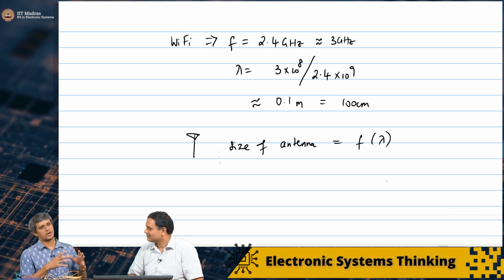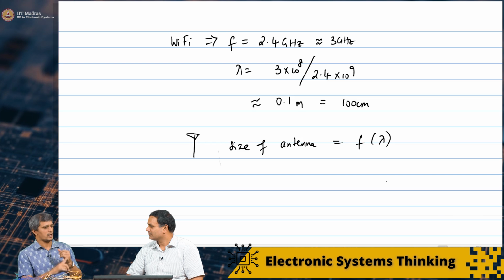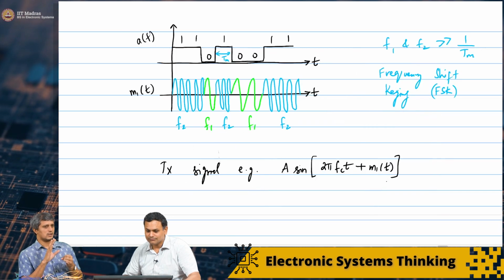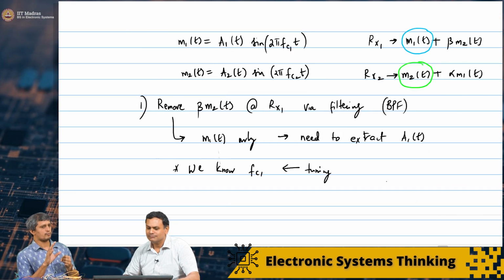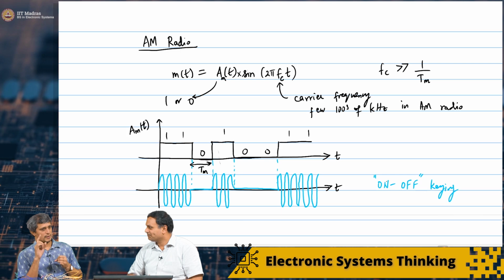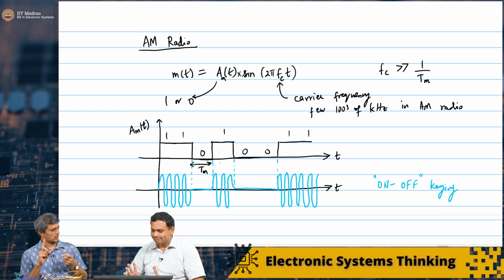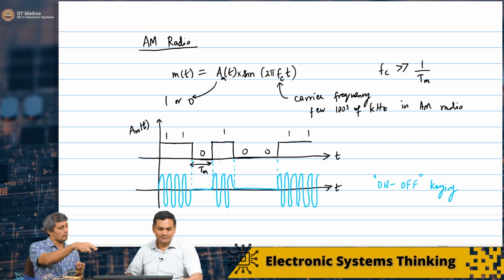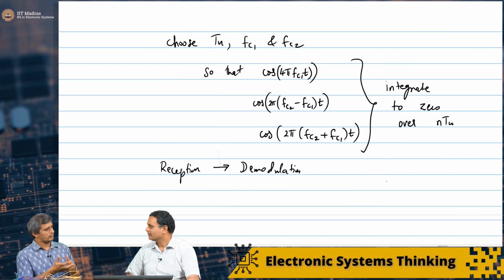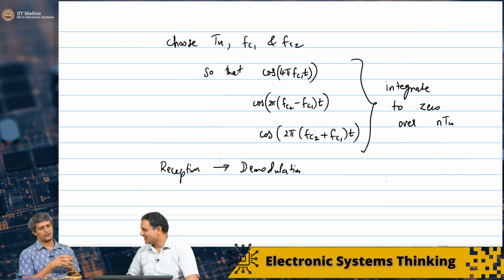I think we have covered the theory in reasonable detail. The primary takeaway is that it is just elementary trigonometry that governs amplitude modulation. There is nothing fundamentally limiting in terms of power. The modulation is not for the sake of power. It is basically to keep your signals orthogonal to each other and not allow them to mix and get garbled. That orthogonality is what we showed with the multiplication and integrating. And of course, FM, you showed some FM signal, but demodulation is slightly more complicated, so we will not deal with that now.